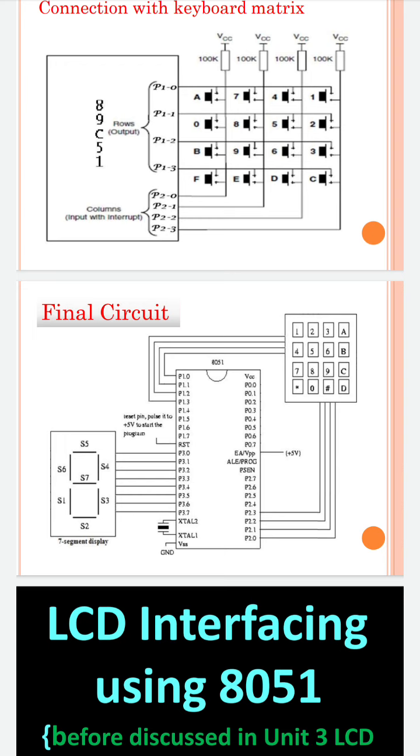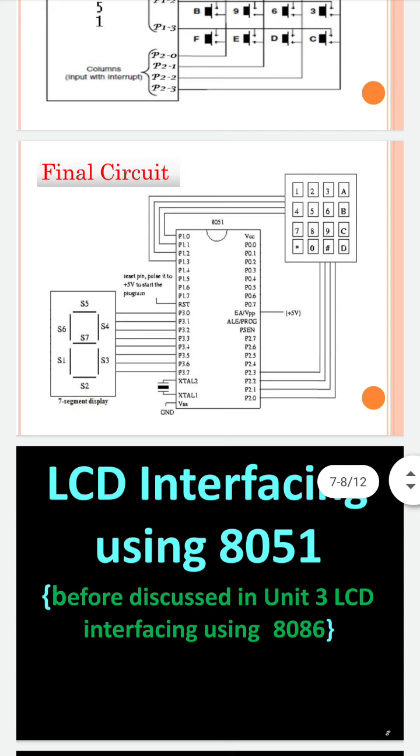In the microcontroller we already know that there are 40 pins, allocated to various purposes. Among them, the first 4 pins of port 1 are allocated to keyboard interfacing, and another 4 pins of port 2 are allocated to the keyboard display interface for displaying the alphabet. Based on the programming, we display the alphabet: A, B, C, D, E, F, and finally G, H. This is a 7 segment LED. We use keyboard and display interfacing in buses and in many other applications.